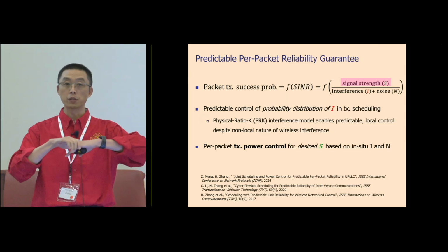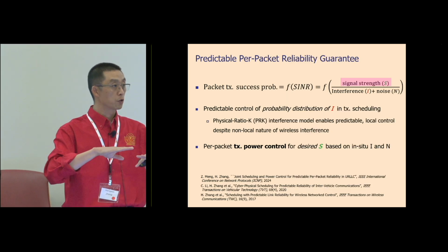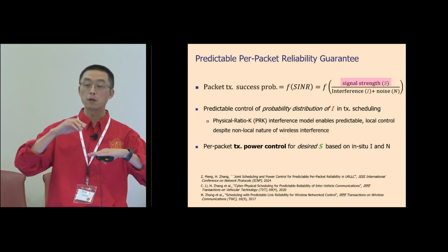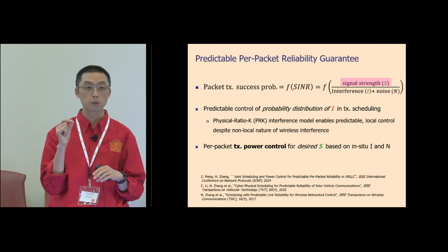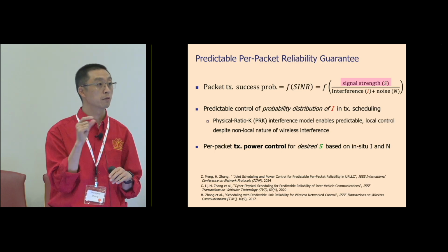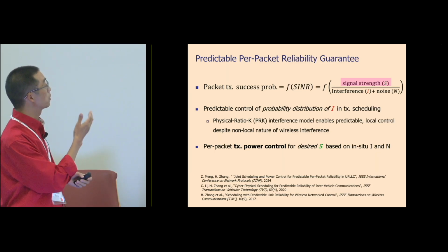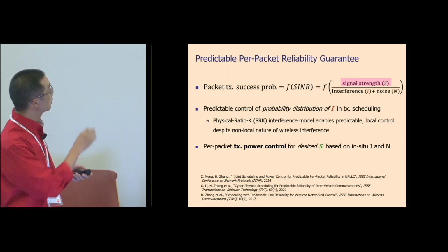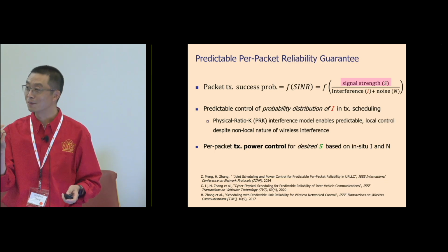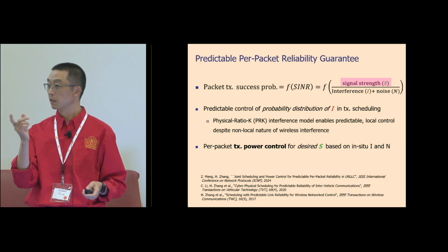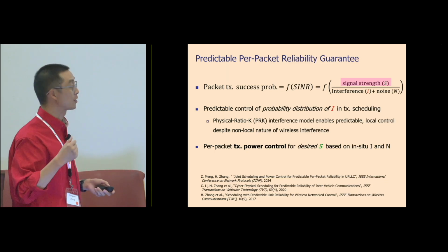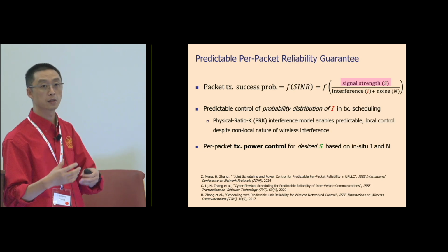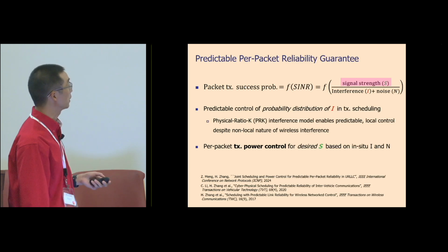Assuming you know the receiver-side distribution of noise plus interference, you then ask what transmission power you should choose to guarantee the distribution of SINR, and you can pick a transmission power depending on that objective. So this is going to be our first mini demo today, which Zibo and Elizabeth are going to show us shortly, showing how you can use the testbed to try out such transmission power control techniques.